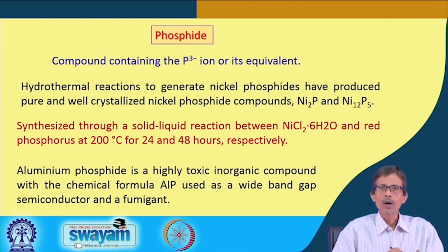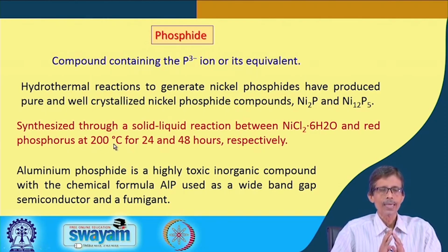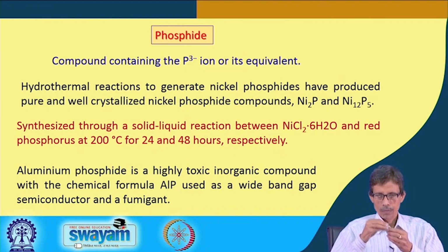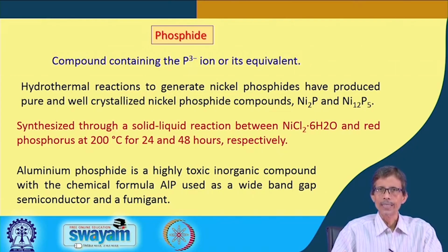So, temperature rise is also well monitored. Throughout the time, as in the example here, we are giving a 200 degree centigrade rise in a time frame of 24 to 48 hours. So, we will be reaching 200 degree centigrade in a time span of, in one case, 24 hours, in another case 48 hours. So, the rate of increase in temperature, in that way we have to monitor it.